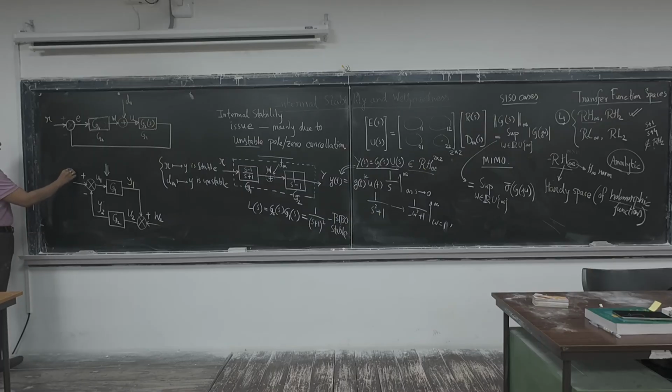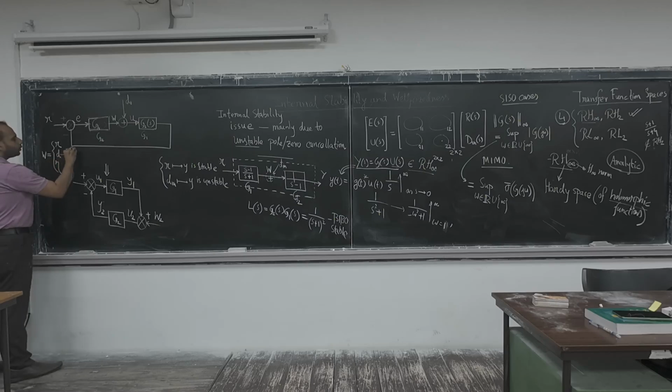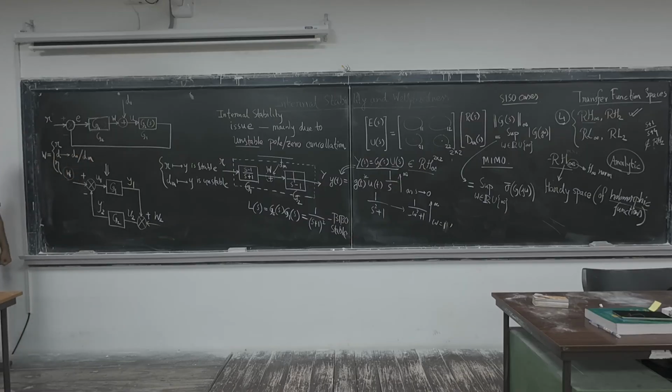So this Y, this W, this signal W, is generally designated for an exogenous signal. So what are the W candidates? It can be R when it is a reference, it can be D when it is a disturbance, it can be eta when it is a noise. Now D can also be D_o, which denotes the output disturbance, or D_in if it is the input disturbance. Okay. In robust control, we will be dealing with 4 kinds of signals.